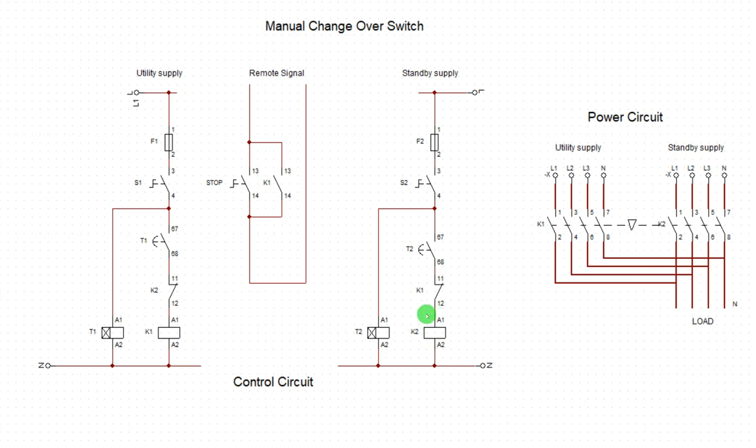Before power is allowed to come in here, I want it to pass through this chamber, through this circuit. I repeat, before this standby power is allowed to come in, I want it to come through this logic so that this logic will permit that instruction for this to close. That is to prioritize this, to prioritize power to this utility. Watch the way I do it.